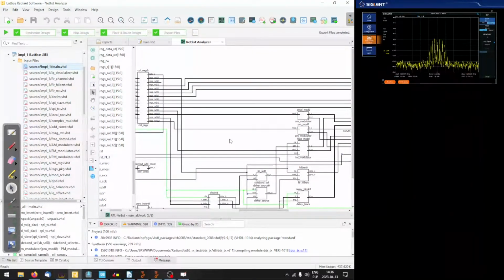Let's first try and prepare the CTCSS block. It's going to incorporate the lookup table, the NCO, and a simple map that would map the 6 bits from one of the registers to the frequency word. And the frequency word is going to be 21 bits.